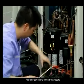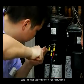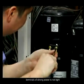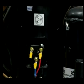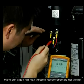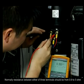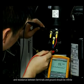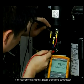Repair instructions when P3 appears. Step 1. Check if the compressor has a malfunction, a short circuit happens to the strong power, or the terminals of strong power are not tight. Use the ohm range of the multimeter to measure resistance among the 3 terminals. Normally, the resistance between any of the 3 terminals should be 0.9 to 5 ohm, and the resistance between terminals and ground should be infinite. If the resistance is abnormal, please change the compressor.